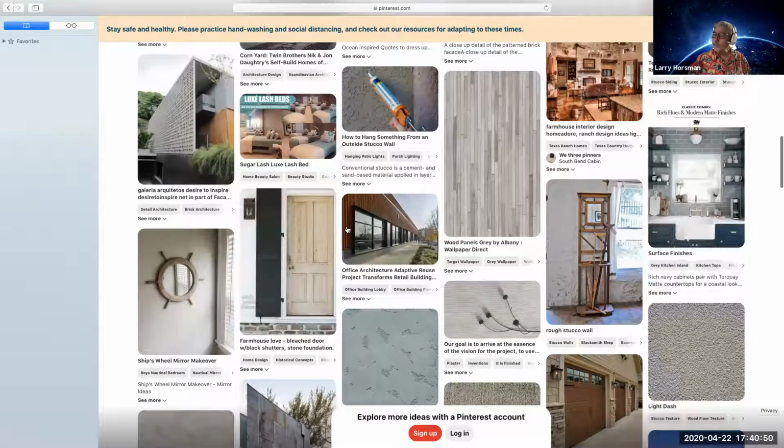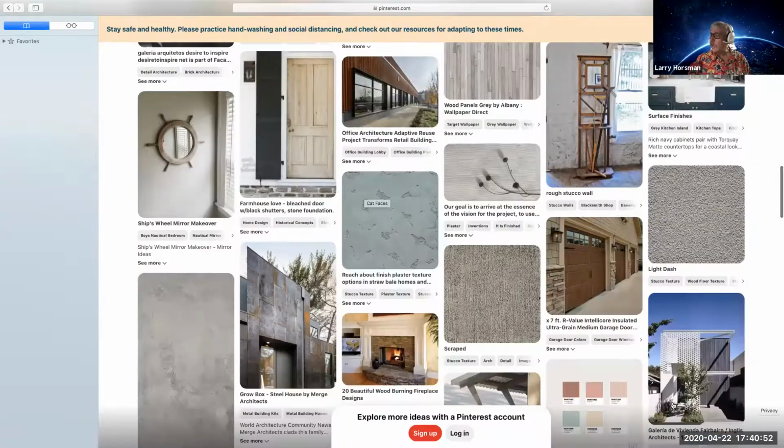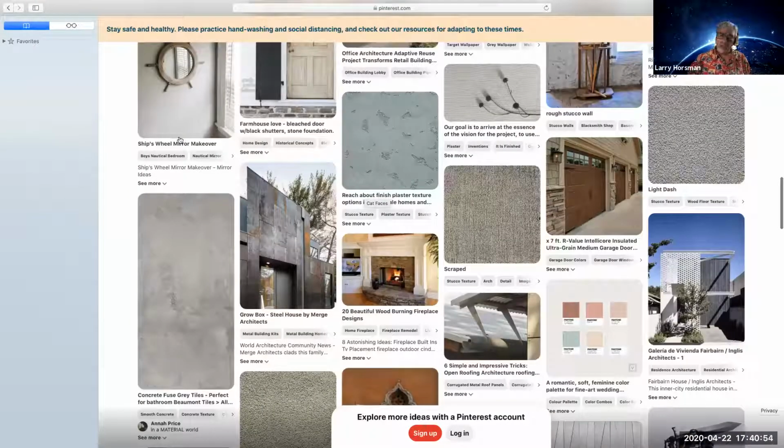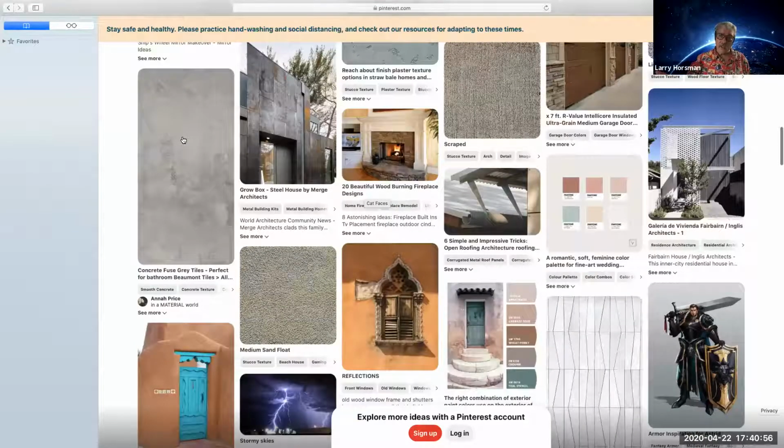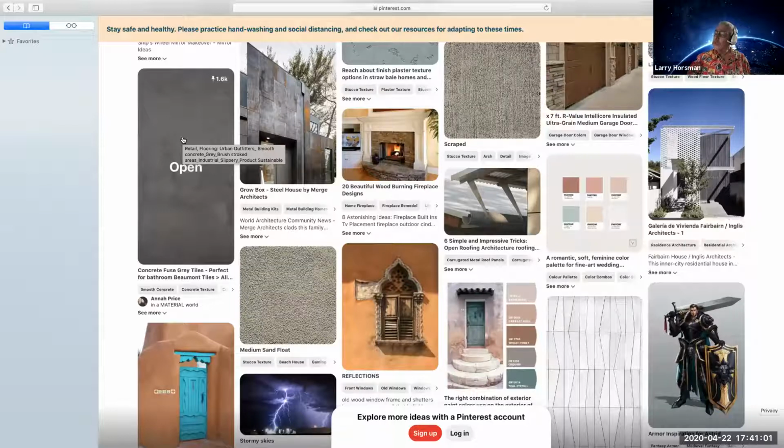So on commercial projects, what adds to the cost is you're going to have to prepare a sample. Usually that's a 1 yard by 1 yard sample, and that's a mock-up. You get the finish to the point where the owner's happy, or the client, the architect, whoever is doing that kind of quality control or administration, and then you keep that sample on the job, and that becomes the basis for whether or not the stucco's okay.